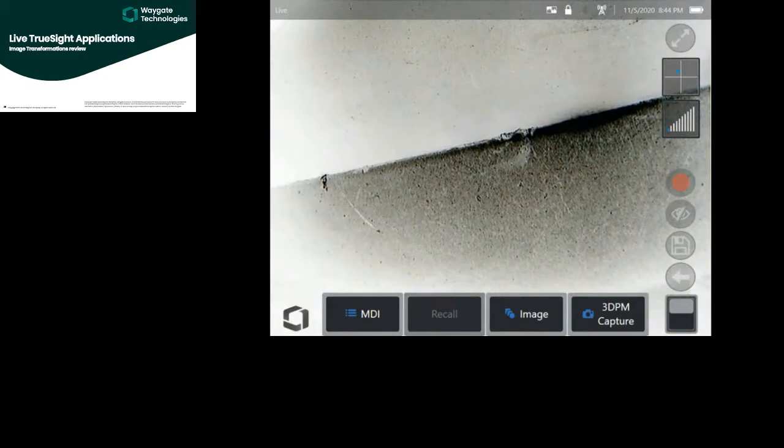And then if you look to the right where that leading edge impact is, and it has somewhat of a white kind of a hook coming just below it, or a smear, but look at what looks like some kind of indication running from the tip of the blade quite a ways down into the face of that blade. All right, look at that indication and watch what it looks like with Inverse Plus off.